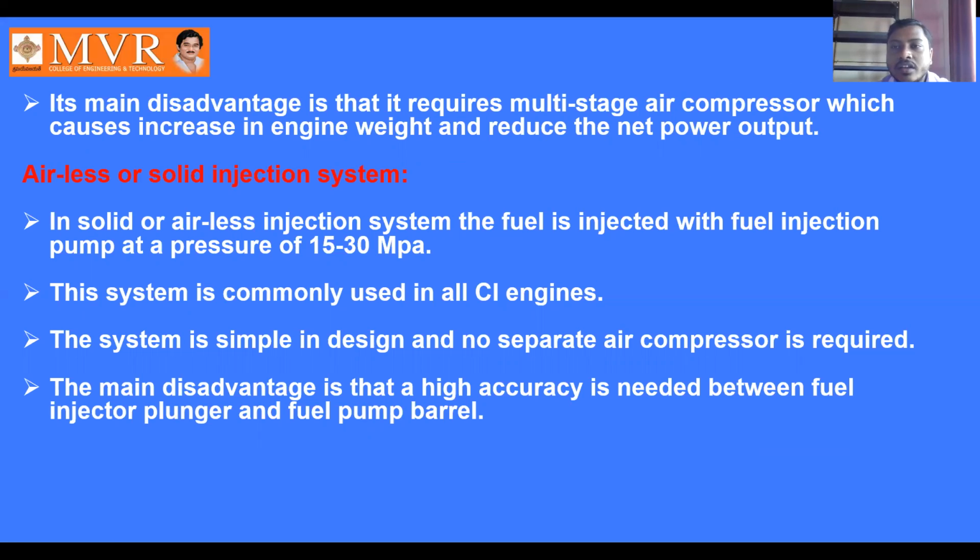This causes an increase in engine weight and reduces the net power output. This is the disadvantage, that it requires a multi-stage air compressor, increasing the weight and reducing the net power output. This is one of the disadvantages of the air injection system.